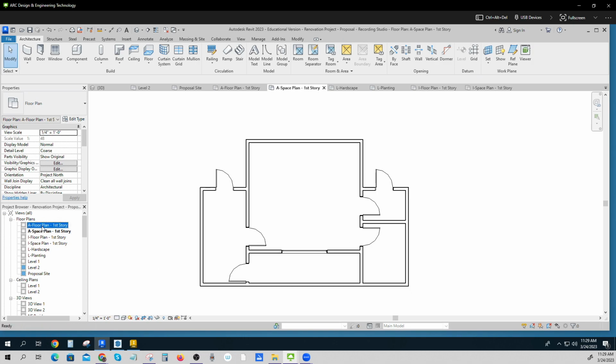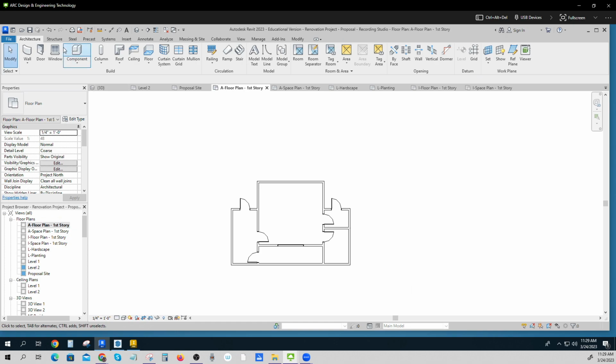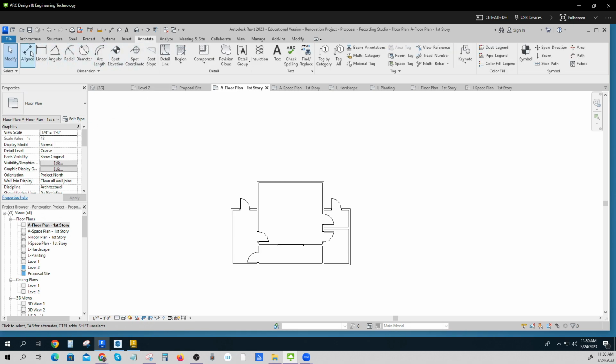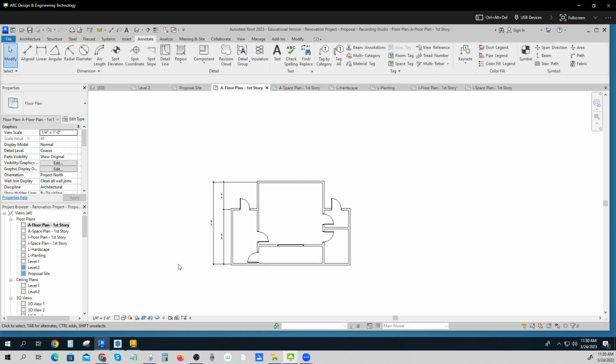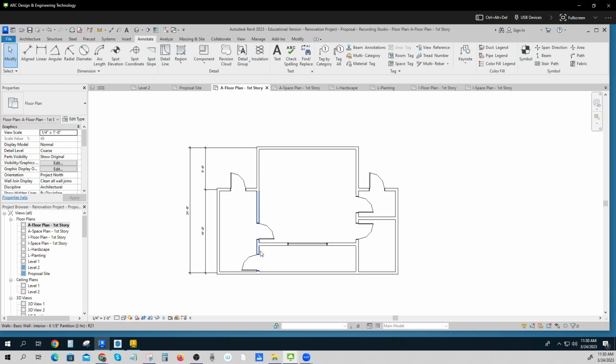Now on my plan view, I said please make sure that we've got the major walls. I'll have to see how big I want this to be. But for right now, 1/4 inch equals a foot sounds okay. And we usually do major walls in one line and then an overall in another line. You would do something like that.